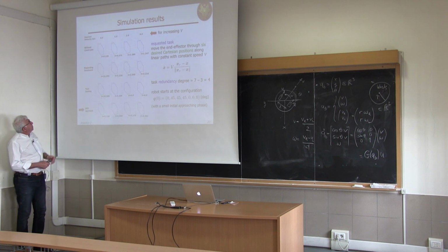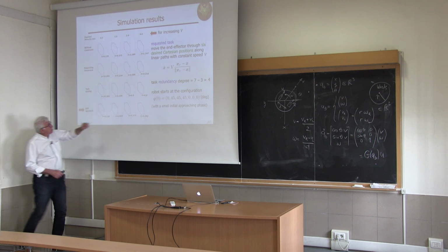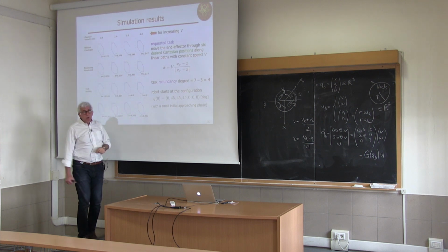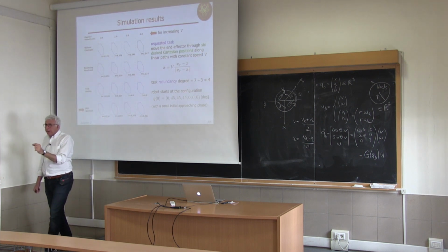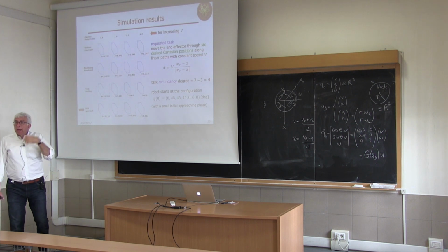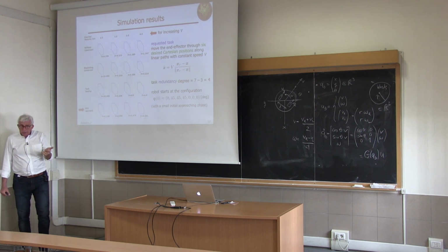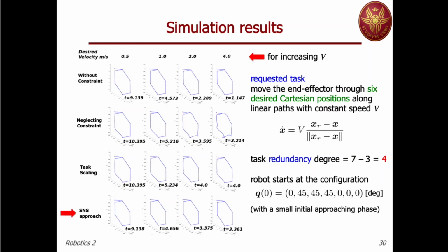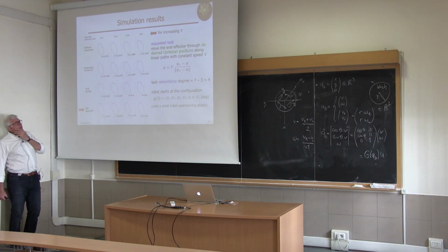And you see that initially with this configuration, you're not even on the hexagon, so you can see a small segment which is an initial transient error, which is being recovered by the presence of a Cartesian controller. So you're not just commanding x dot, but you're commanding x dot desired plus some positive gain k times the error between the desired x and the current x. And once you are on the path, then you will keep this.